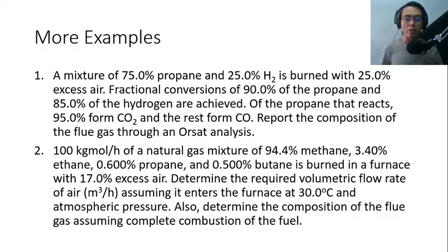Okay, now take note that in problem number 1 you have CO in your product, or in your flue gas. So your flue gas here would contain CO2, CO, H2O, O2, and N2. Now, how much CO2 will be formed? How much CO will be formed? It's stated here: 95% of the propane that reacts will form CO2 and the rest will form CO. So factor that out in your calculations.